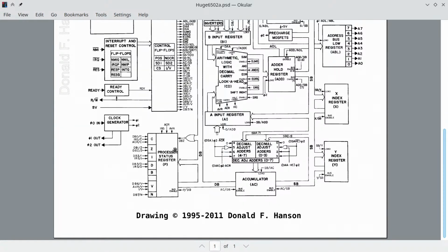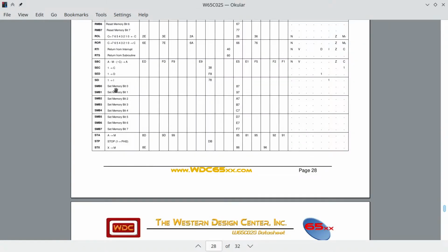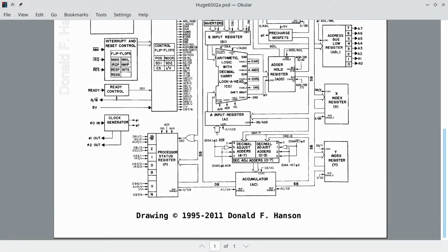So right now we won't need the ALU. So what we need essentially is to set the, right now we're on the carry, right? We're on set carry. So we need to set the carry to 1, which means we need to generate a 1 on the data bus. But that's not how we're going to do this.